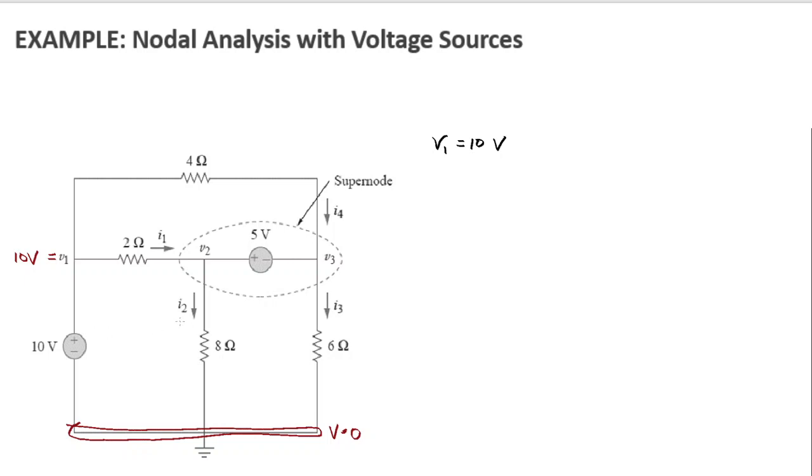Case 2, if a voltage source is connected between two non-reference nodes, apply KCL and KVL, or make that a supernode. The connection of them is a supernode, and then apply KCL and KVL to solve for V2 and V3. Like a supermesh called loop X, as you can remember, let's call this supernode, supernode A.